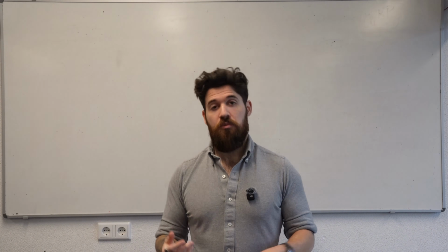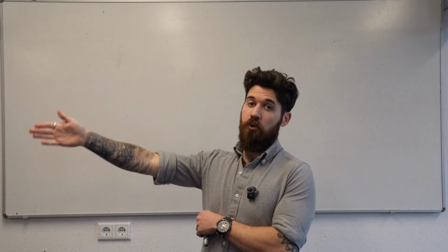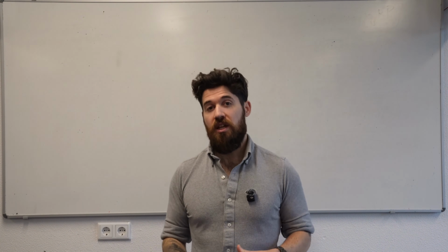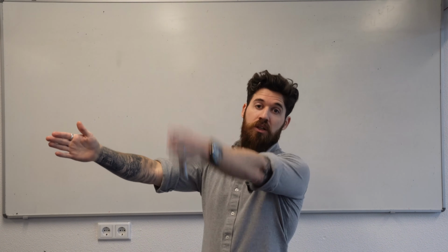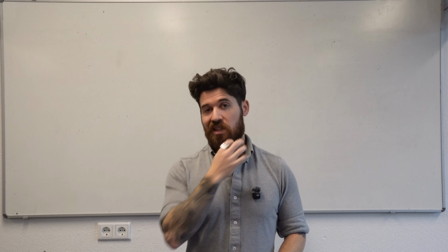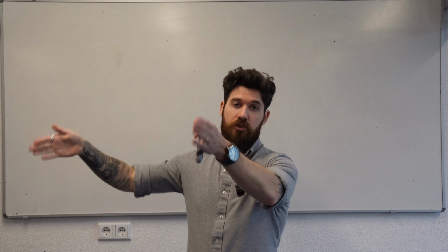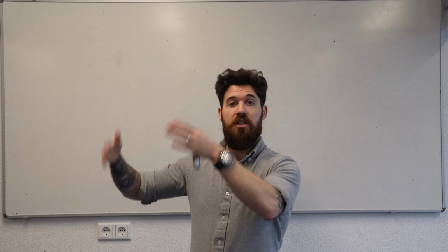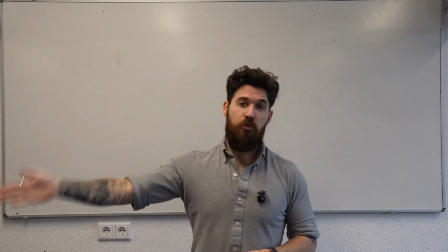Here is how derivative works as opposed to proportional, where you look at how far away you are from your goal: if I'm really far away, apply lots of power, and if I'm really close, apply a little bit of power. Derivative is instead applied based on a time base. So you might have reading number 1 and reading number 2. If the readings are really far apart, it's a large gap. That means you're still likely far away from your target, and that you're probably moving really quick from reading 1 to reading 2.